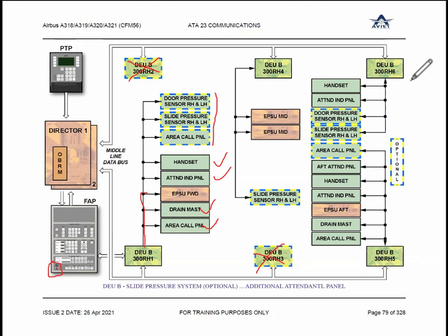Secondly, why is the pressure switch optional here? In earlier design, when they started, it is a headache actually to know the pressure. If a pressure switch is provided, it is good, but it is an extra element, extra component. So you have to look for maintenance, pricing, and all these things. Or alternately, what Mr. Hitham has said, there is a pressure gauge, you can go and check whether the pressure has leaked. If you don't have a pressure switch, you will not come to know whether there is pressure or it has leaked out. Are you getting my point?